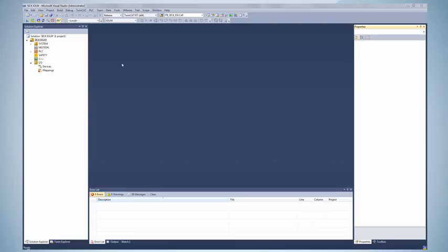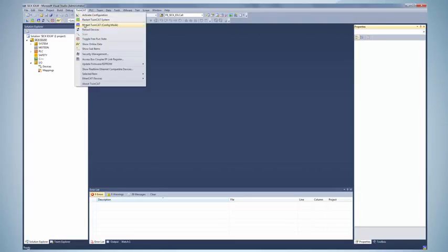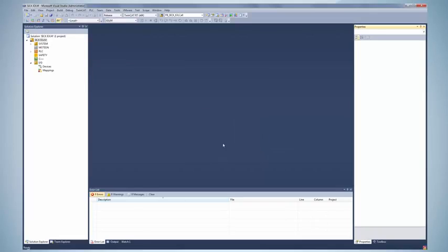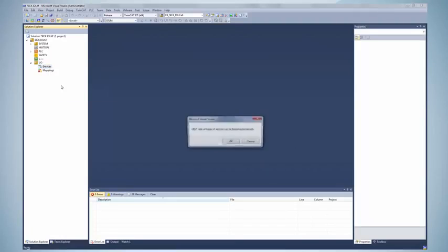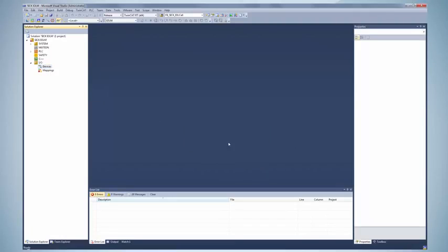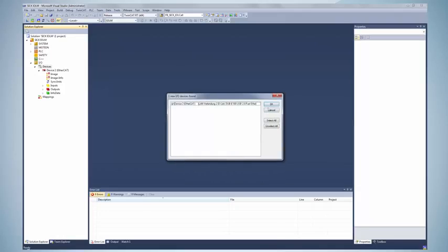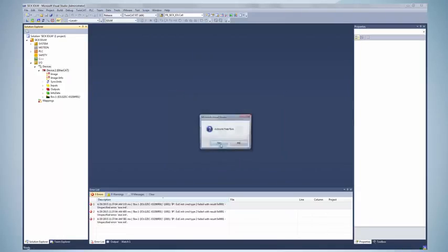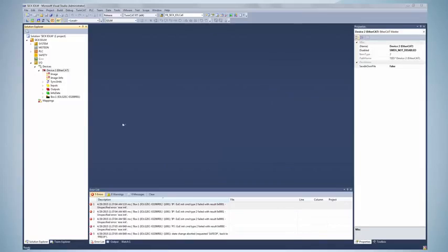First of all, the PLC needs to be set to config mode. Only if the system is in config mode, it is possible to scan the hardware. Please select here your network access and scan all connected Ethernet slaves and activate free run. The I/O link master shall now appear in the tree structure.